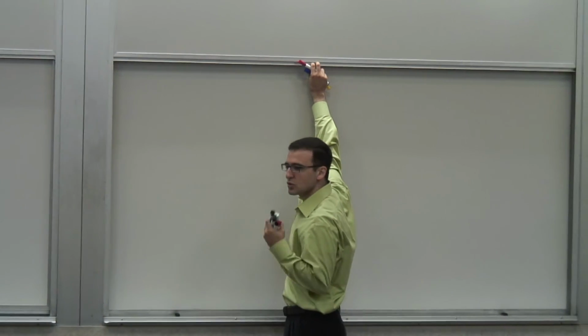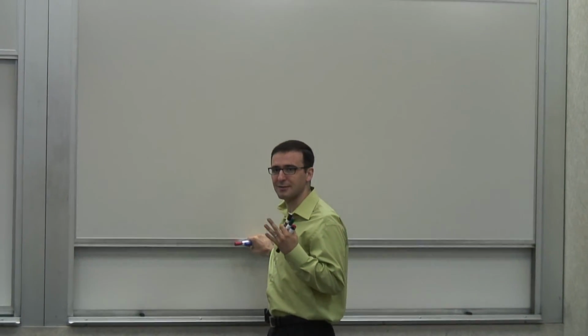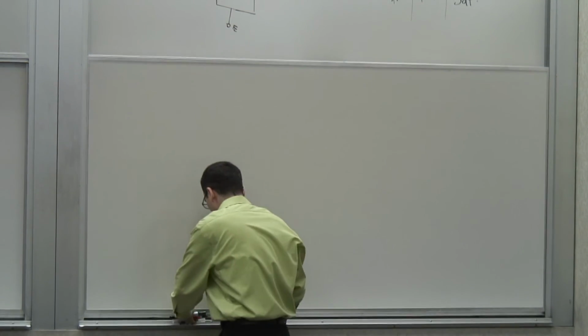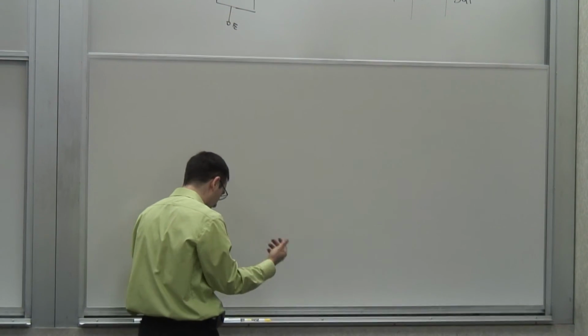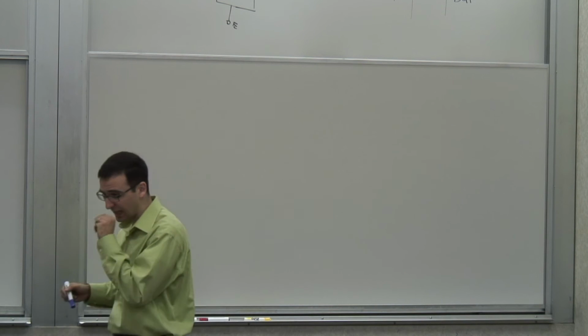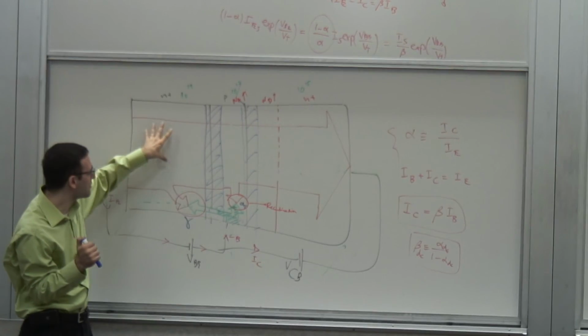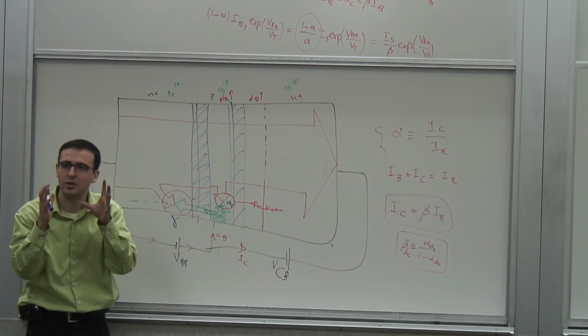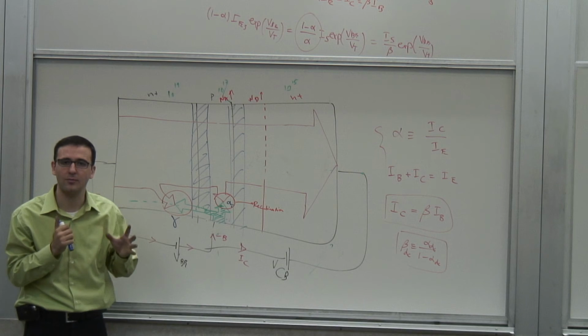Okay, now, so far, everything we've been talking about has been kind of static, low frequency, DC kind of thing. But now let's see what happens in the transistor when you start moving things a little bit faster. One of the things to keep in mind is: what is the parameter that really controls the collector current in this picture? Well, it is really this voltage, but what is the thing that really controls how much collector current you have at any instant in time?